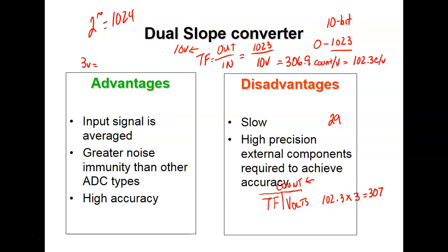Well, you have to know the in and you have to know the out before you can calculate transfer. Yeah, well, the problem is I said 10 volts, but you're right, I didn't write it up there. This is pretty standard, by the way, on PLCs. 0 to 10 volts is pretty standard for the analog inputs. This guy right here, 0 to 10 volts.